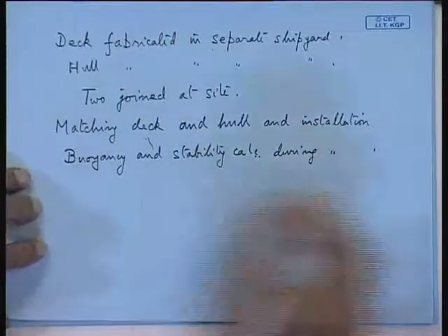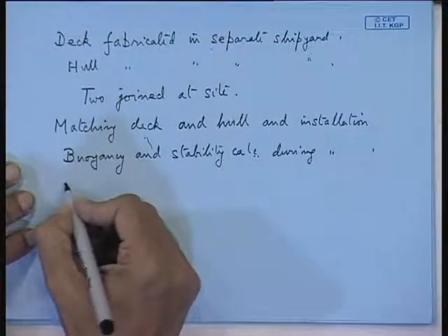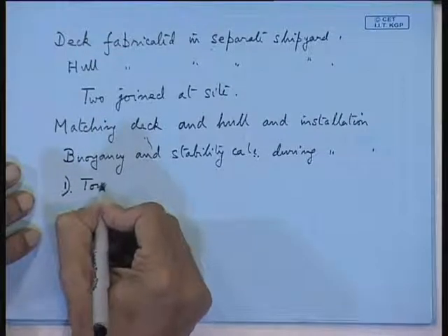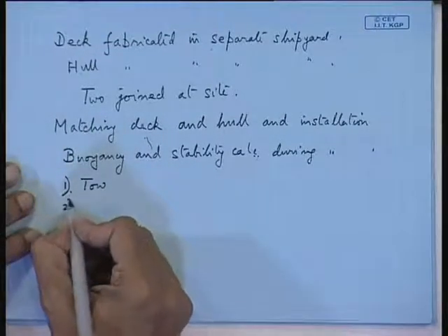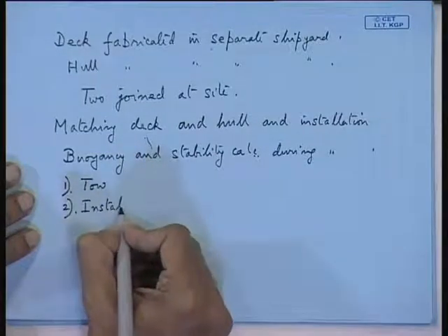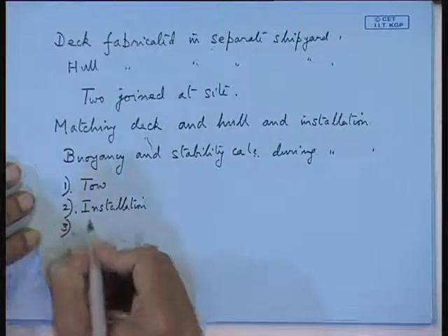First, you have to do all these buoyancy and stability conditions during what? During tow, then during installation, and the last one is in the operation phase.